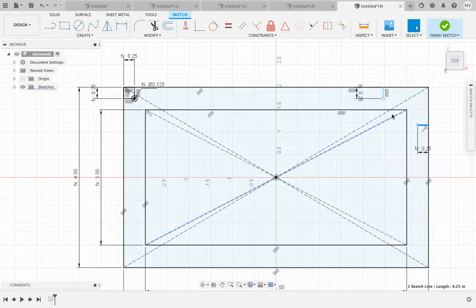We have a tool for that. We have a constraint for that. It's the coincident constraint. Coincident puts 2 points together in space. So I click on the first point, end point of this line. I click on the other one. They lock together. And they're fully constrained now. They can't go anywhere. Those points have to be at the same place. They have to be a certain length. We're good to go. And that looks really similar to the sketch that I did in this corner, right?